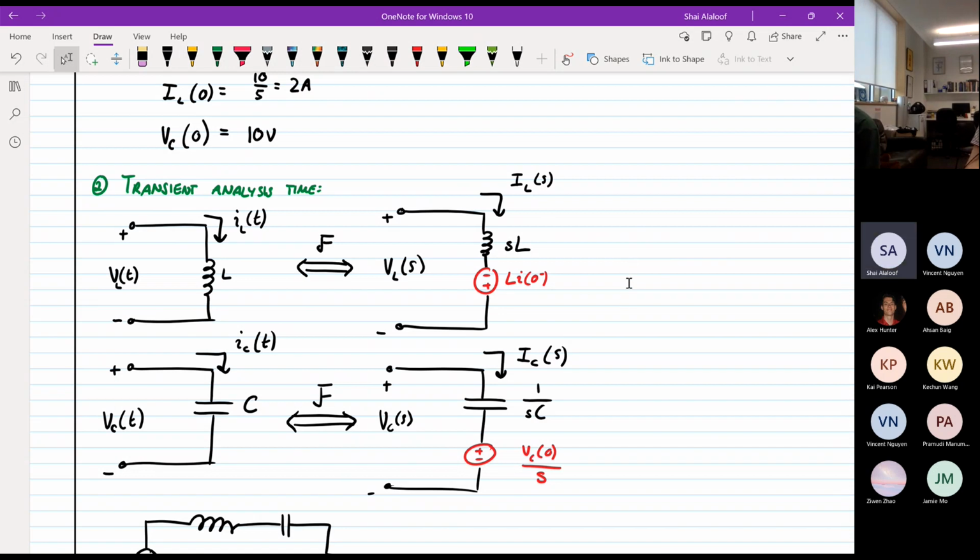I recommend just sticking with memorizing one, or since it's open book, I'm pretty sure the equation is in the slides. If Julian doesn't have slides, it's definitely in the textbook. It's also on my formula sheet, which I will also share. But yeah, the value of this voltage source in series is going to be equal to L times the initial current. So as you can see, it depends on the initial current. That's how you're taking into account your initial conditions, essentially.